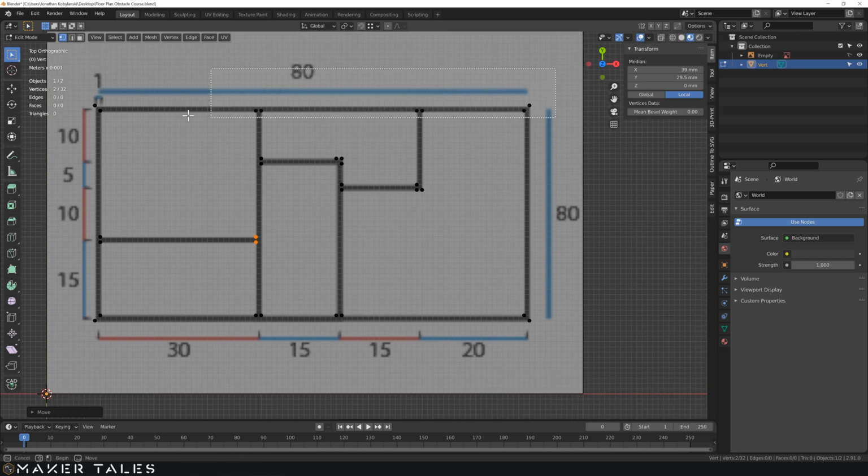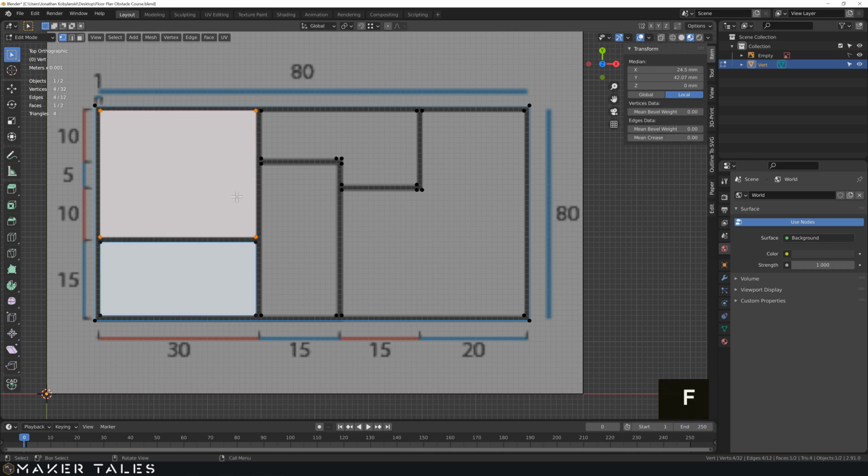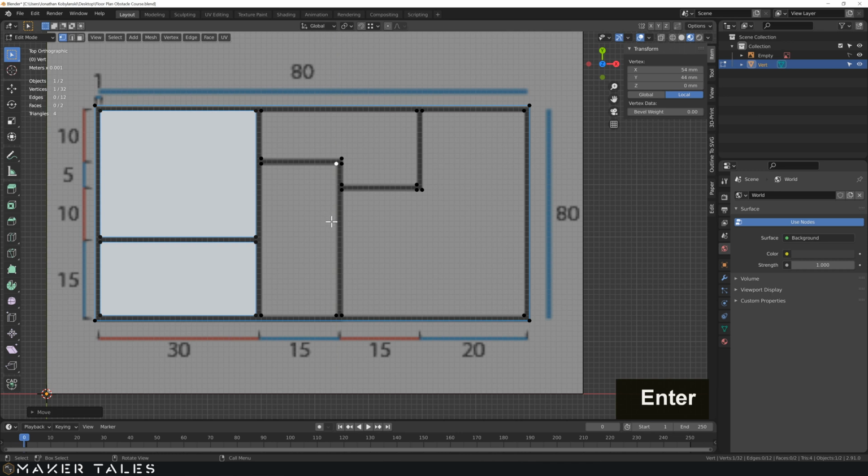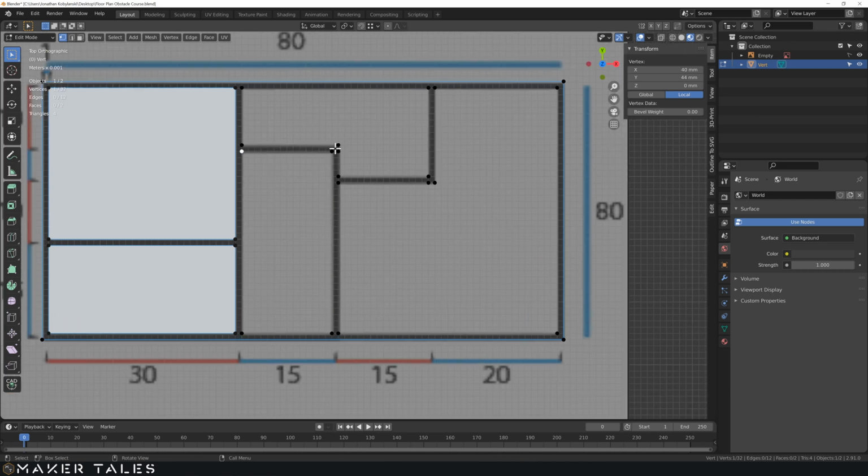So let's go ahead and do that. Let's select all these vertices here and let's start fusing them. So we're fusing these here, fusing those there, fusing these right here, and fusing those there. Now, you know what, we're just going to select these in 4s now. So let's select these 4 and fill that. We'll go ahead here, select these 4 and fill that. We'll then actually grab this one, go G Y minus 1, move that to the correct space,